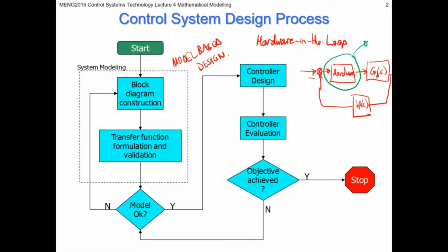That's your control input, and then your control action comes back into your plant model in the software, and then the behavior of the plant or the behavior of the system is modeled based on that control action. You get your feedback loop, and then you get your updated control action fed into your hardware. So it allows you to actually build the control hardware before you have a physical plant.